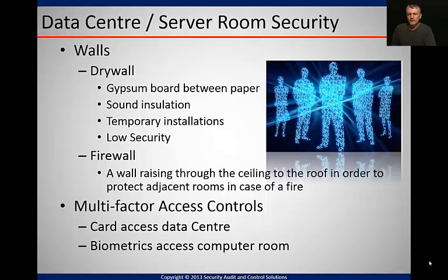We have drywall, a gypsum board between paper or cardboard. It can also be used sometimes just for sound insulation. Temporary insulation definitely, and it gives us very low security. A firewall is a wall that comes from the foundation at the bottom right through the ceiling, right to the roof, to ensure that it protects adjacent rooms in case of fire.